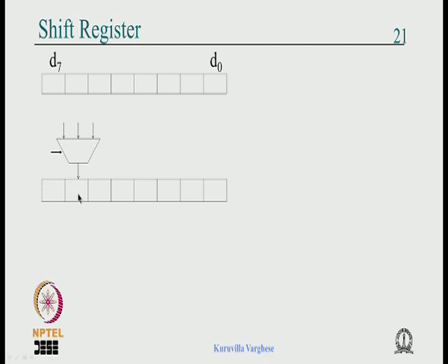So I am showing a scheme wherein, say, you take the Q6, the D6 part, I am showing just one. If it is a shift left, then the Q5 is pushed here. If it is shift right, the Q7 is pushed. If neither is true, then the same value can be pushed. Okay, now it depends on the select line.